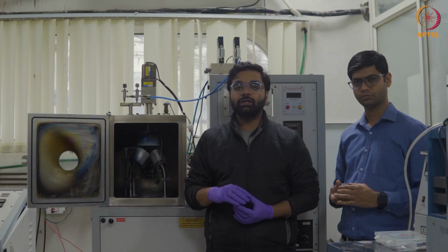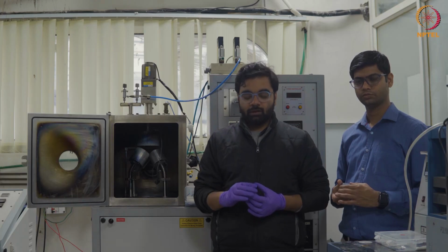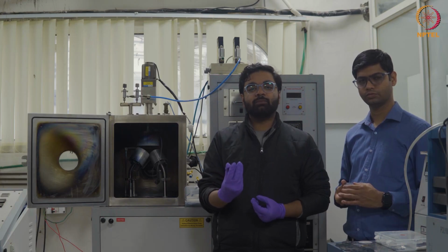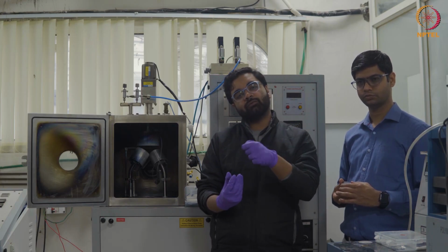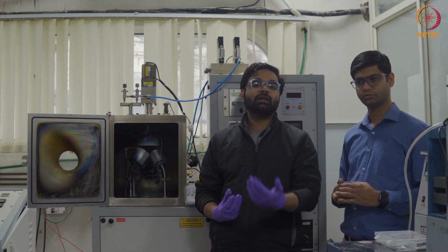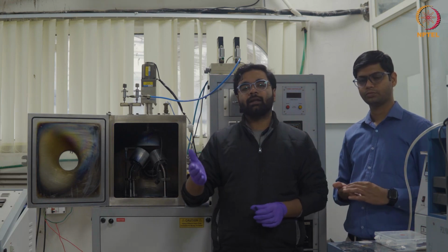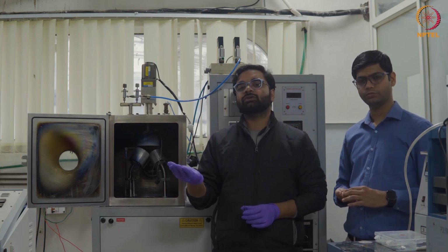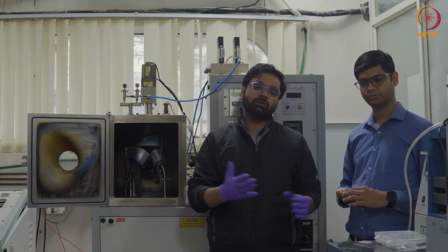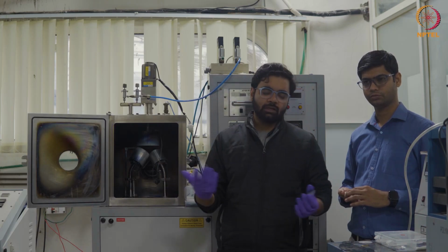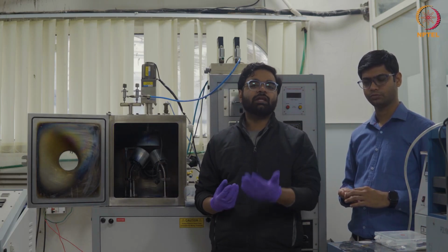So conventionally, the simple principle is we take this silicon wafer, put it on a vacuum-based spin coater, and on top of it we put 1 or 2 drops of PDMS. The PDMS ratio that we use is 10:1, PDMS A to PDMS B. The PDMS polymer has a main solution and a binder, and the solution to binder ratio is 10:1 that we conventionally follow. Of course, it can also vary. People use 8:1, 6:1 to 14:1, depending upon their application. So we use 10:1.